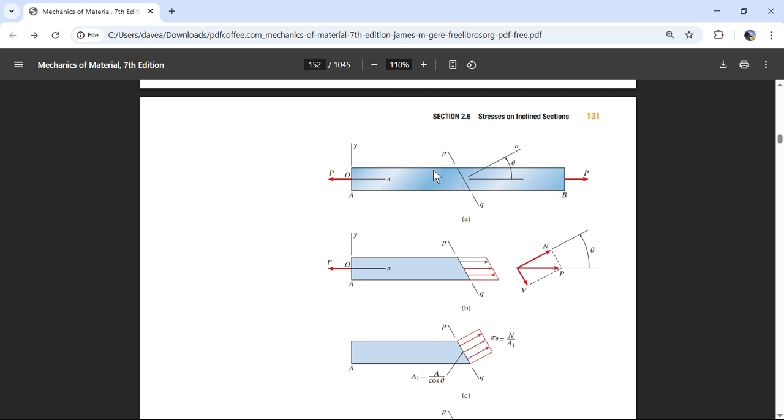Or I could put a line right here and put a force this direction and a force this direction. On that same 1-inch area, I can only put half. I can only put 29,000 pounds. So it's kind of fascinating that when we do this free body diagram, we get this shear force to be 70% of 58,000, which is much bigger than 29,000 pounds.